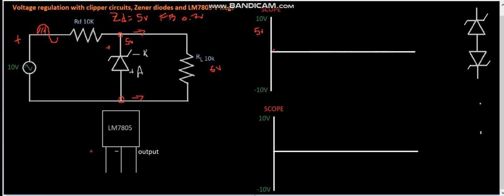So we're regulating the voltage, aren't we? I mean, that's really what we're doing. We're regulating that voltage. If this is conducting, we get 0.7. If it's in reverse bias, it's going to drop 5 volts, and we've got 5 volts, so 5 and 0.7.